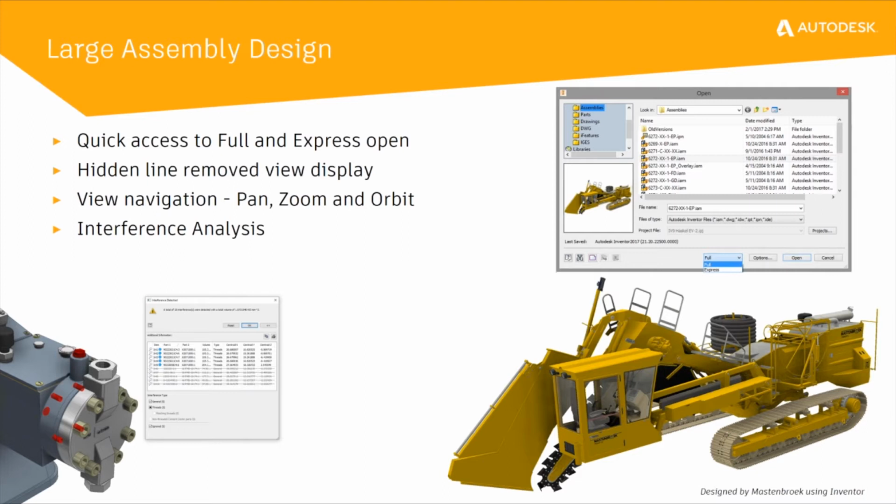And then we've added additional workflows with existing tools like assembly interference analysis, where you can start treating sub-assemblies as individual parts from an interference perspective. You can ignore certain interferences that maybe you want to be interferences, like press fits, things like that. And you can also go ahead and start looking at interference between threaded fasteners and holes. So you can start seeing if there's an interference just between thread types, between those types of geometries.